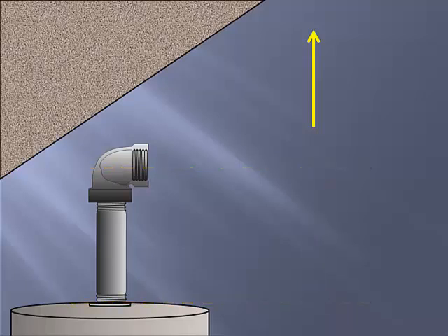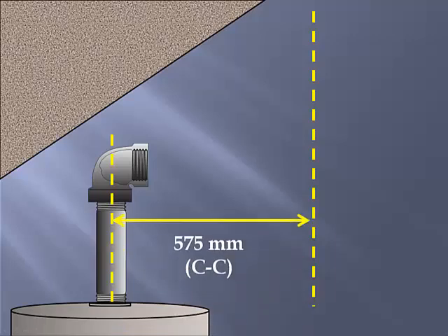to about this location. What we'd like to work on for today's lesson is how to take a center-to-center measurement, subtract for the fitting allowance, to accurately cut the end-to-end piece required for the offset. First, we're going to establish two vertical lines to take a center-to-center measurement from the first piece of pipe with its fitting to the location of the next fitting. So we take that measurement and we find that the center-to-center measurement would be 575 millimeters required.